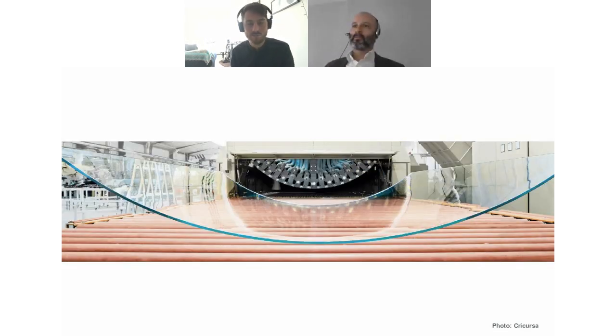On the other hand, to get a bit of curvy glass, which is all the rage, there's this method here, which is tempered bending. So here we've got a temper furnace, and the machine, you plug in the radius that you want, and the machine will bend it to the desired radius, which is great because you can get all sorts of different radiuses. The first panel can be 2 meters, and then the next one 2.5, and there's very minimal cost implications for that. You get strong glass, and you get all the coatings you could wish for. The issue with this method is that it's just cylindrical, not S-shaped, not conical, just basic cylindrical forms.